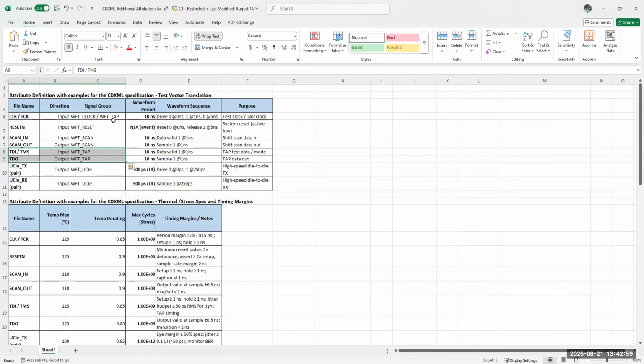One test pattern can have multiple waveform tables, and so when the tool translates it, it has to align the data when it is forced and when it is strobed based on the clock window, right? When it is cyclizing it. So that cyclizing information is tied based on the attribute name called signal group.